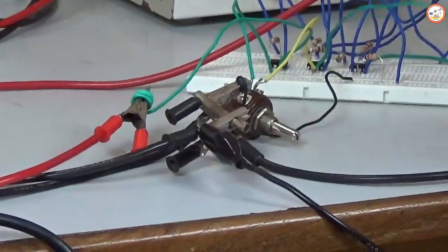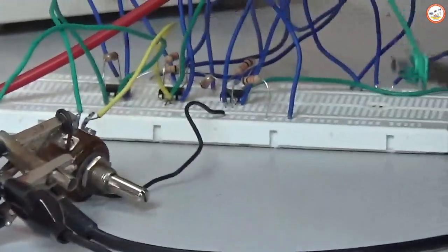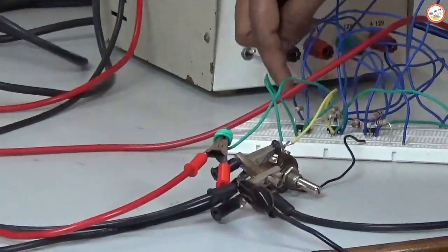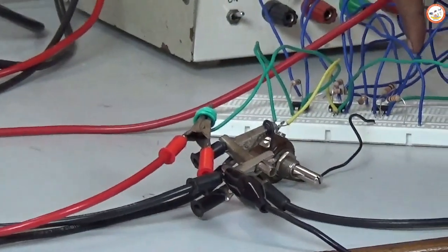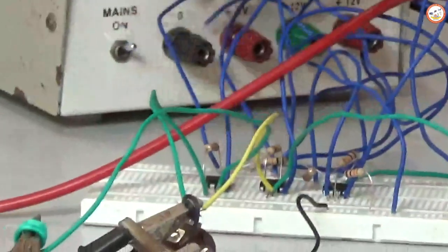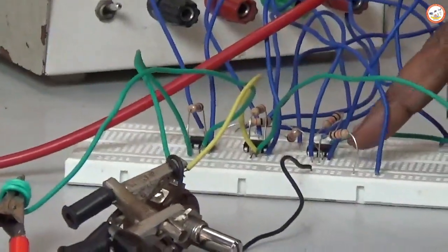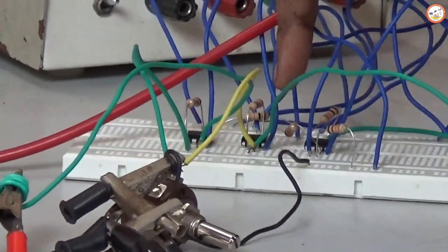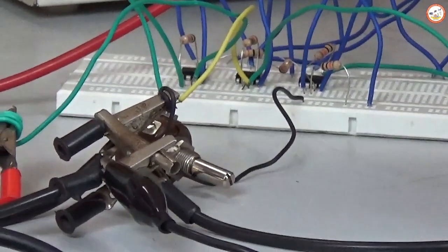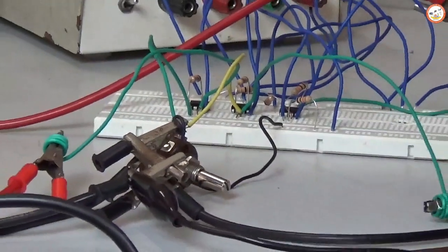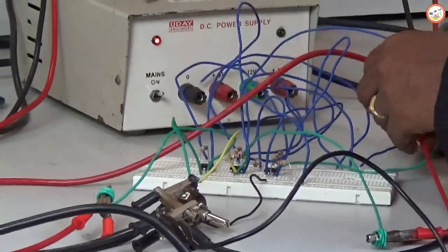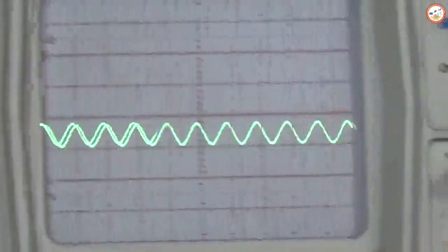Input is given to the second IC pin number 3. The first input is given to pin number 3 of the first IC. This is the first IC, second one, third one. Then connect the final one: the first IC 6th pin output, which is connected through a resistor to the second pin. Similarly, the second IC 6th pin is connected to the third pin. Then the final output is taken at pin number 6 of the third IC, which is connected to CRO. The amplified version of the signal you need to get.